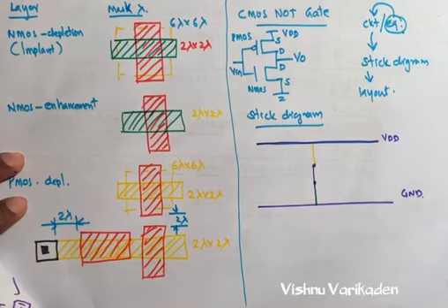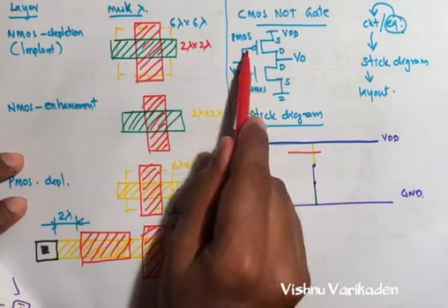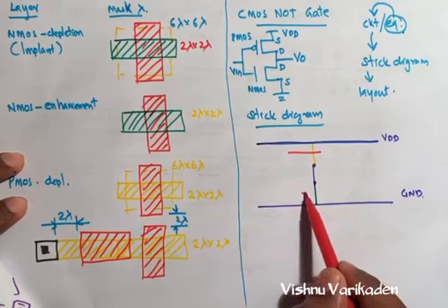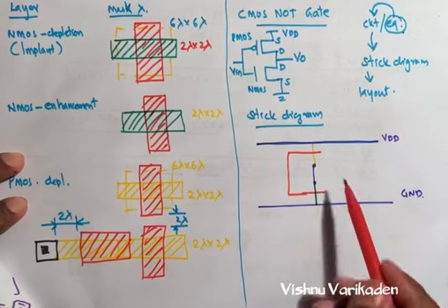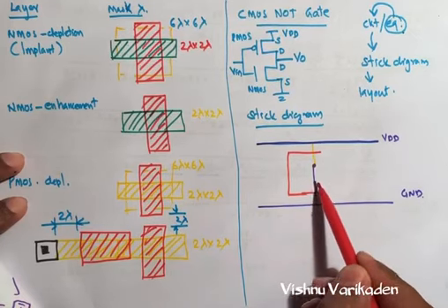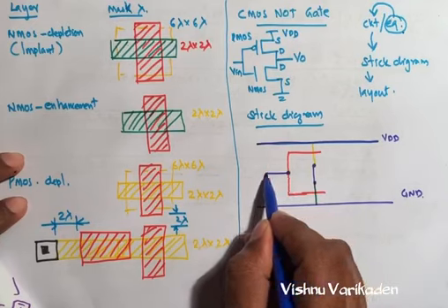Next we can make the transistor. So the transistor is made by polysilicon. So this gate is connecting to this gate. So we can create the PMOS, and we can create the NMOS also. Next we can make the terminal of the gate. So this one is starting from a metal.